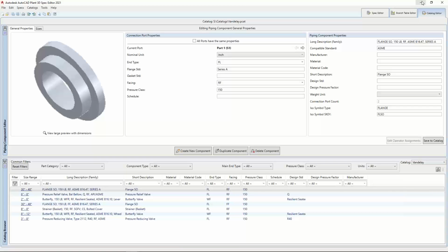And I'm a proponent of separate catalogs so that when I go from one version to another, I don't have to transfer all these different settings over from one catalog to the other. I can just point at my new catalog and my specs will work in the same catalog. I've been using these same specs for years and not having to do anything to my catalog because I keep all that customization separate. So that's why I'm going to put not only my bolt mapping standard in my catalog, I'm going to have to put bolts that reference that standard in the same catalog. So here's how we do that.